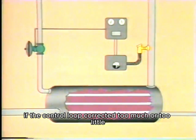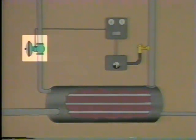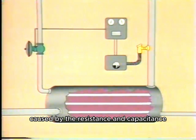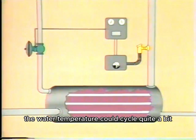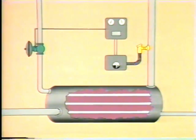If the control loop corrected too much or too little, it would eventually be sensed and a new corrective signal produced. Because of the delay in temperature changes caused by the resistance and capacitance in this process, the water temperature could cycle quite a bit before it returns to set point.